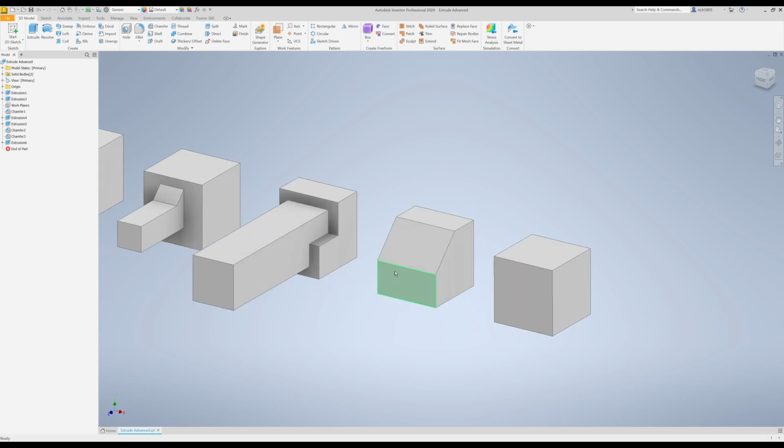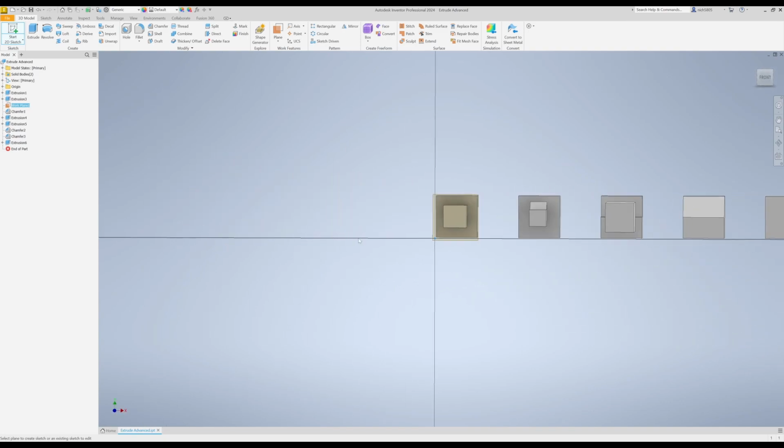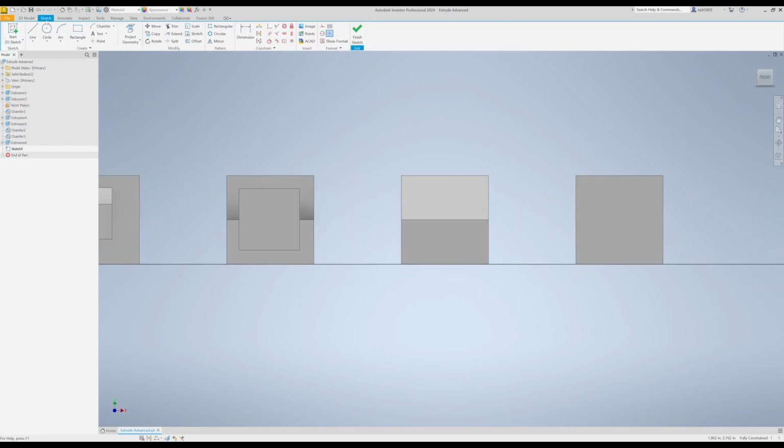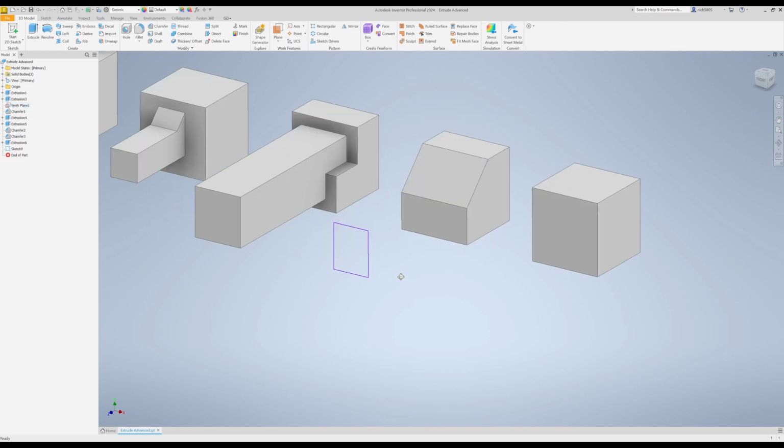This will also work on slanted objects, I suppose. Let's turn that work plane on again. Start a new sketch. And let's make another rectangle. Just a random size right there. And hide the datum plane again. So I'm hiding the datum plane by clicking on it and holding down Alt and then V. It lets you go back and forth. Very nice.